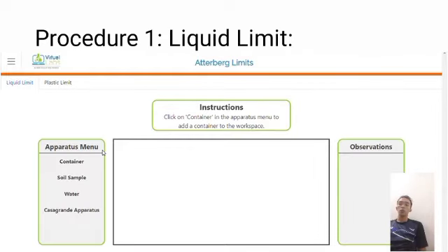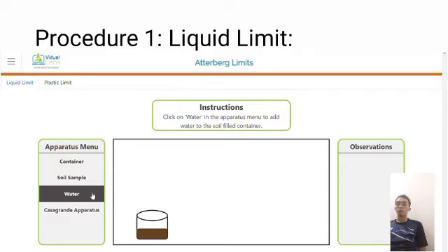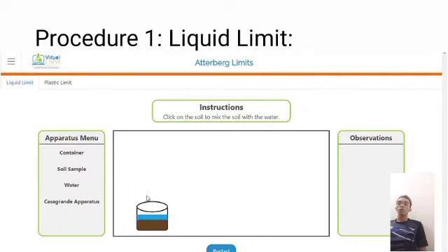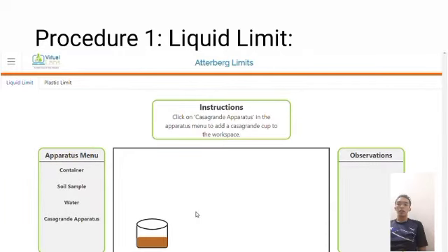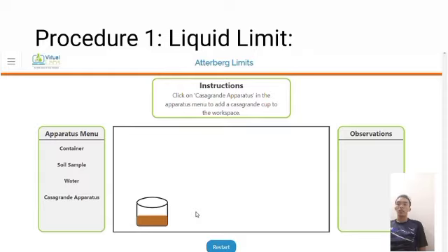Now we move on to procedure. Sieve the soil by using number 40 sieve and take roughly 3/4 of soil and place into the porcelain dish. The soil is mixed with a small amount of distilled water until it appears as a smooth, uniform paste. 4 moisture cans are weighed and the respective weight and can number are recorded on the data sheet.